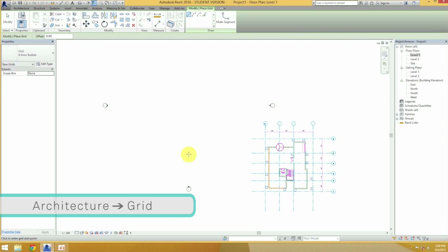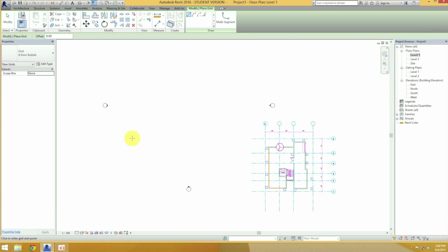We will first do the horizontal grid lines. Near the bottom of the workspace, drag a grid line from left to right. Now make sure that when you draw the grid line, your line snaps to the 90-degree mark indicated by the line. Next drag another one just above it. And with the second line selected, you can see there will be a dimension in blue indicating the distance between the two.